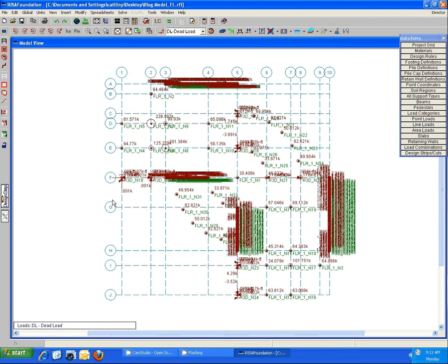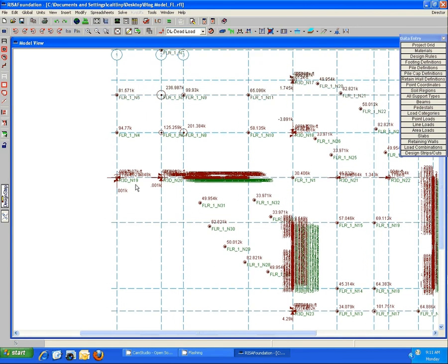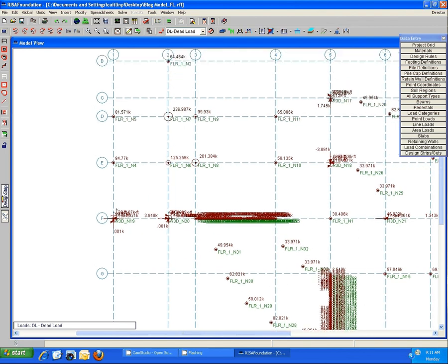So just to confirm that, let's look again at grid line 1, and we can see we have loads here at 3 locations. If you want to look at it a little bit closer, we can see that at grid location F1, we do have a node here called R3D and 19. So that confirms that this loading was the lateral loading that came from the solution from RISA-3D. And then at D and E, we have nodes called floor_1 and 5 and floor_1 and 4. And those confirm to be just the gravity loads that carried over from your RISAFloor model.